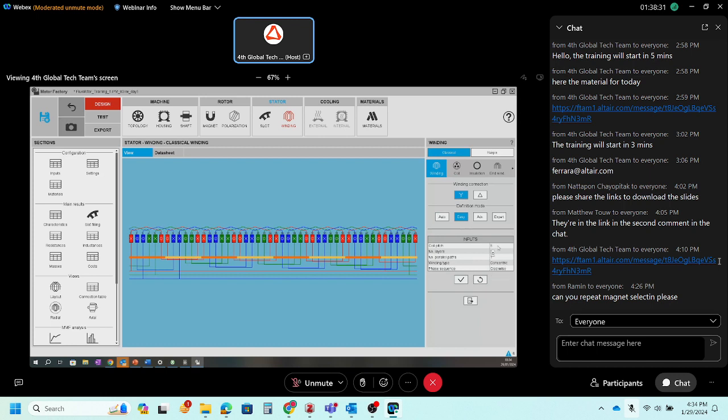As you can see, some more parameters are available to define our winding. The advanced one, to end with the expert one, where we can define the connection table, so called coil per coil, enter slot and outer slot to define each coil in our model. In our case, we can keep the auto.